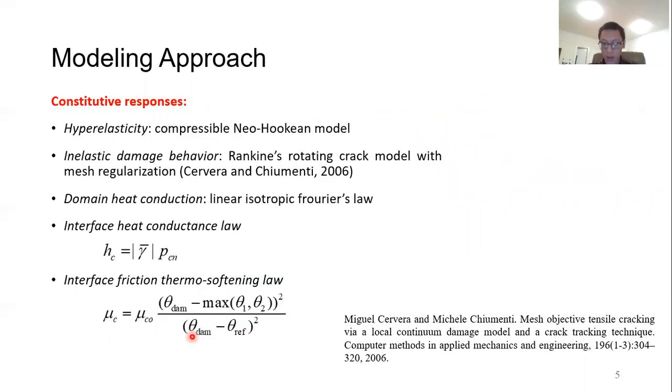This slide presents the constitutive assumptions we use for this framework. We assume the continuum body to be elastoplastic material, where the damage field is important for characterizing the failure, which functions as a continuum damage approach for dynamic fracture modeling.